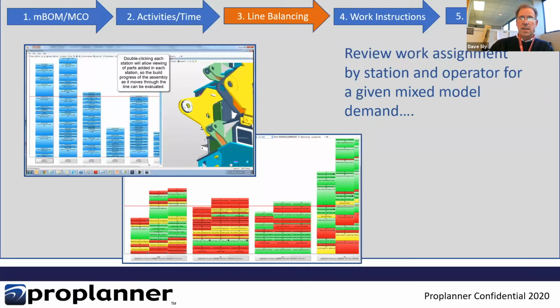And so once again, we do want to look at how long the tasks take. This is a Yamazumi chart. You can see at the bottom here, the 3 bars that are grouped together represents 3 different models of a product being made in a station. The gray bar at the very bottom reflects these stations, or actually in this case, these are operations, because we could have more than one operator in a station. We might have multiple gray bars working parallel in the same station.